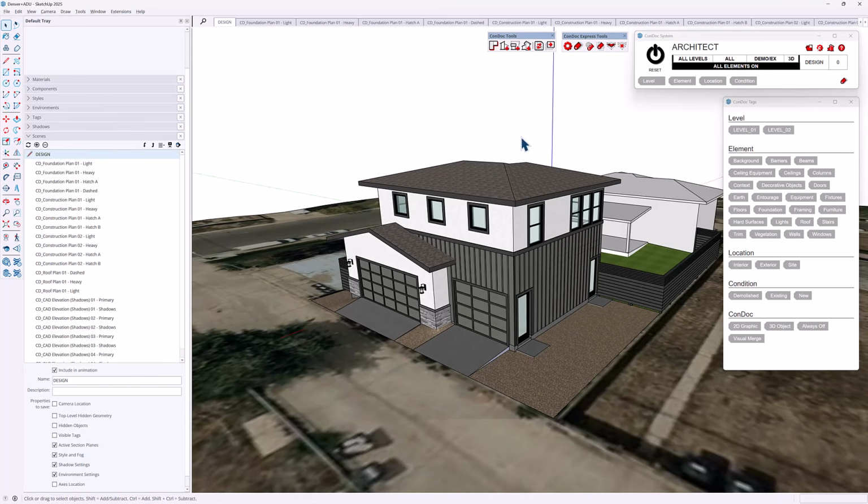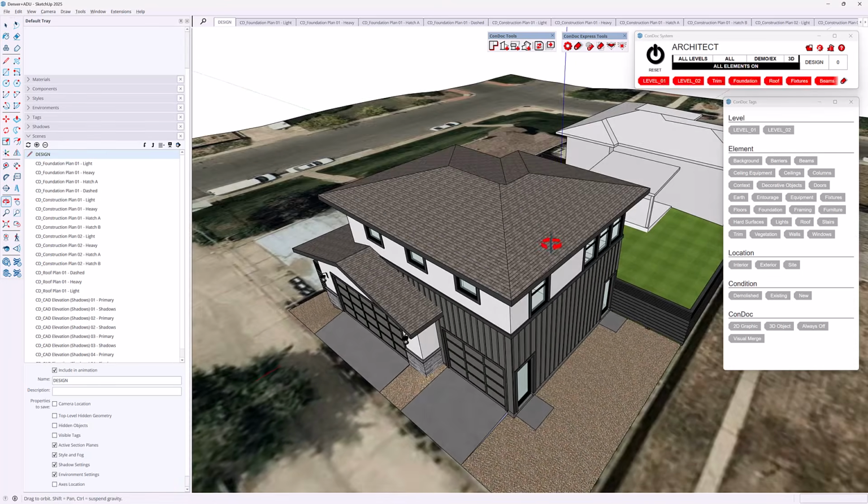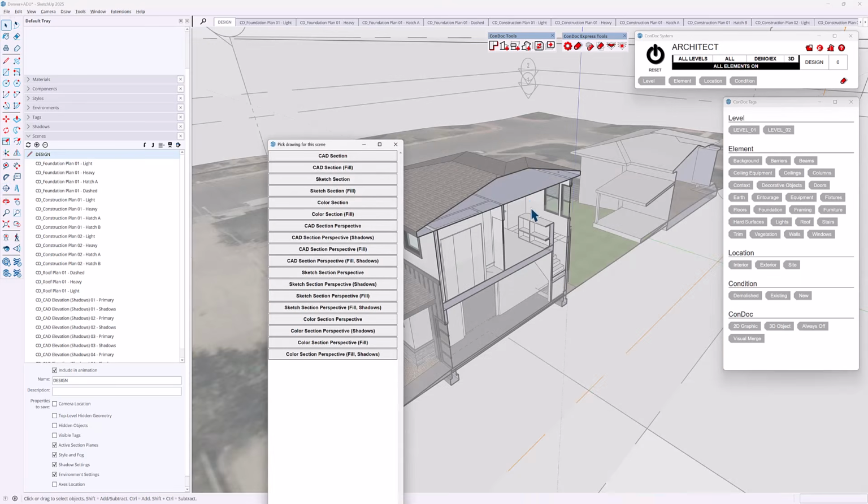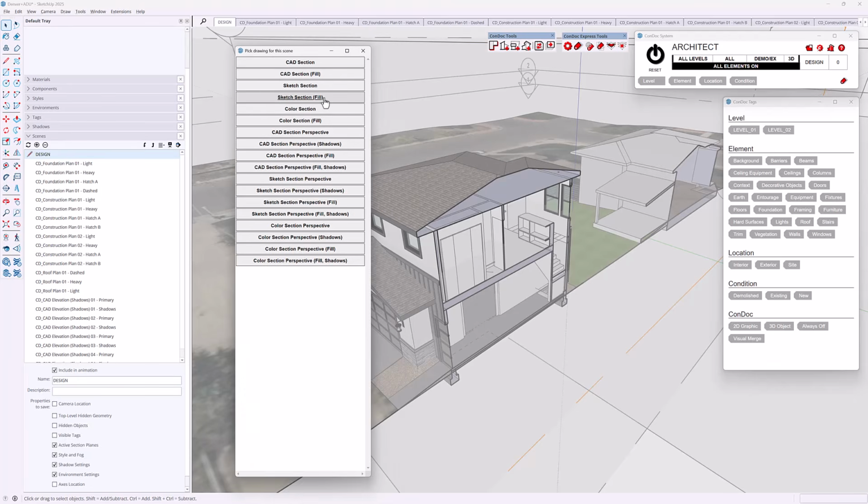I would create the elevations, or list the elevations next. And then I would go to a section. With the section tool, I'm going to tap the left arrow key to lock that on the green. What happens sometimes is if you find yourself mousing around all over the place while the section tool is active, and then you go and click, sometimes you lose the section tool.